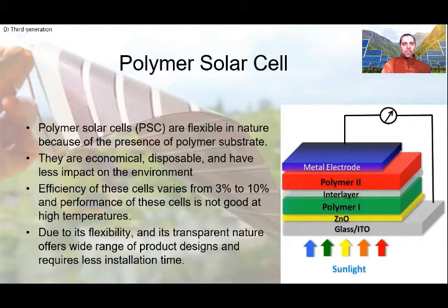The excitons migrate, transporting energy but not charge, because they have no net charge, to the heterojunction, where the built-in electric field will dissociate them, the electron being injected into the other material and eventually making its way to the reflecting metal electrode, while the hole remains on the other side and moves to the ITO electrode.